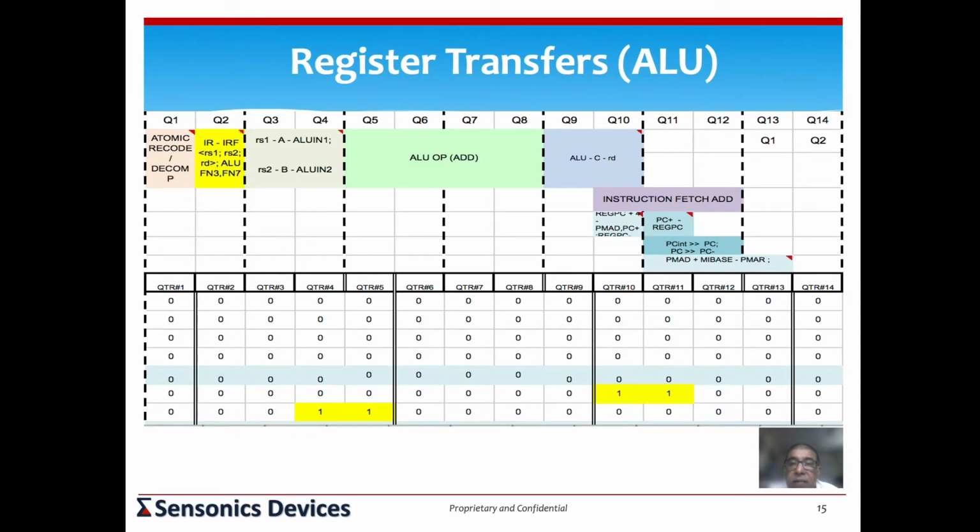So this is the beginning cycle. You've stolen that cycle from somewhere, from somebody else's instruction. But not just that. If you had these ALU instructions back to back, this one would be on the 13th cycle, it would also be on the 5th cycle, it will also be on the 9th cycle, because the previous and the previous instructions would have this operation filling up there. So during those phases, if the data path has no conflict with that particular resource, you can potentially do that.